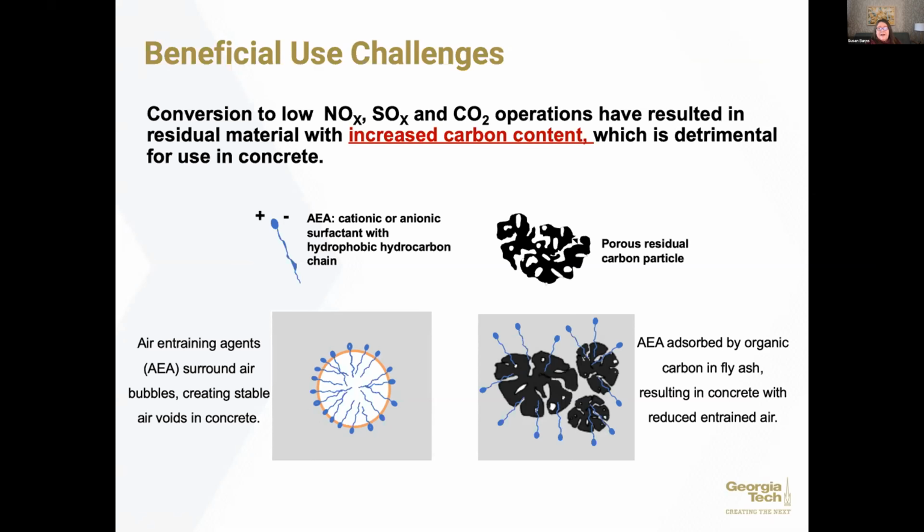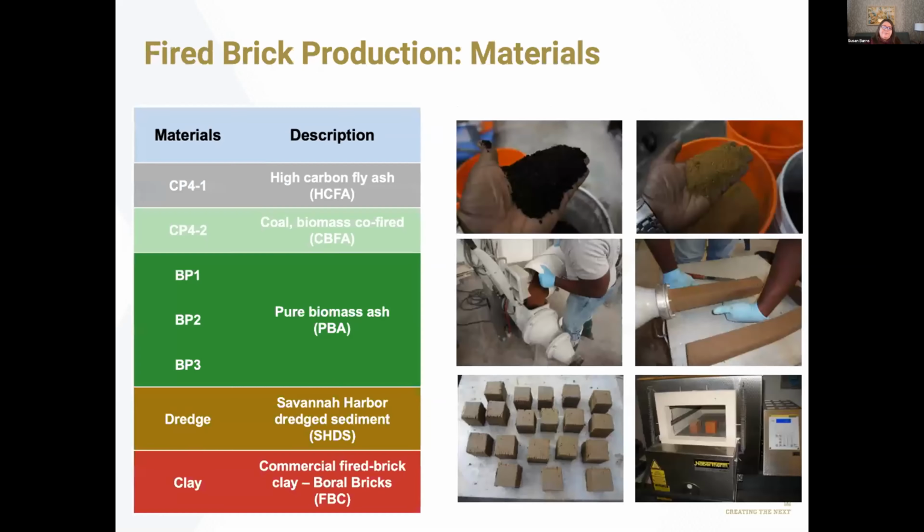What happens when we have a high organic content, though, is that those organic particles will sorb the surfactants. And what we'll see there is we have to add more air entraining agents, which are expensive. So it's costly to us. And so that's one of the reasons why we want to avoid high carbon contents in our concrete.